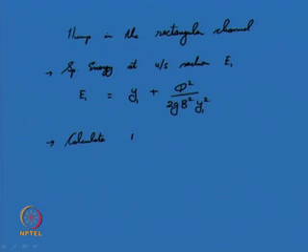So, E1 you know for the rectangular section it is nothing but y1 plus q squared by 2g b squared into y1 square. Now, calculate E2, that is the specific energy at the downstream section. E2 is equal to E1 minus del y.